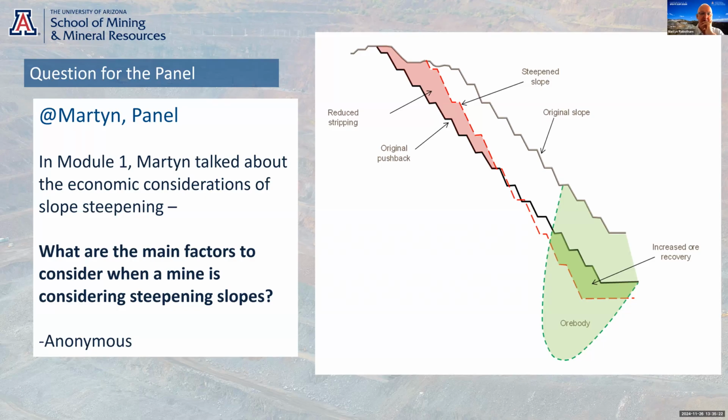Because an interesting question comes when you have very, very strong rock with very limited geological structure. I often find these a huge challenge because when you look at the rock mass, which has no major through-going structure, you've got a very strong wall which stands up vertically for possibly great heights. Then you're flipping things around to not having maybe a major global instability, but managing rockfall over double and triple benches with vertical faces.